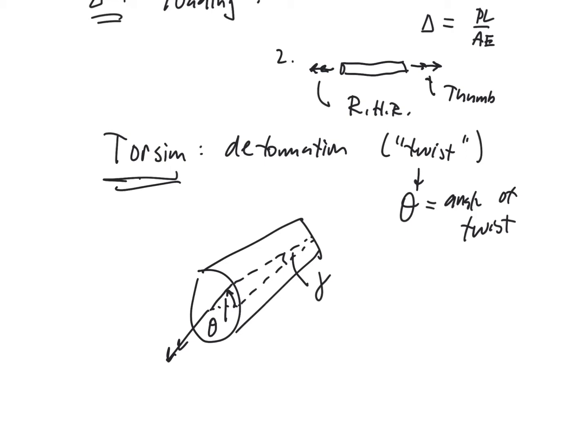And the reason we study this second is because the axial is driven by purely a normal stress and a normal strain. Torsion, I'm going to abbreviate it here, is driven by a pure shear stress and a pure shear strain. So it's kind of nice because in the one problem, we only have one type of stress, and now in the second one, we only have another.